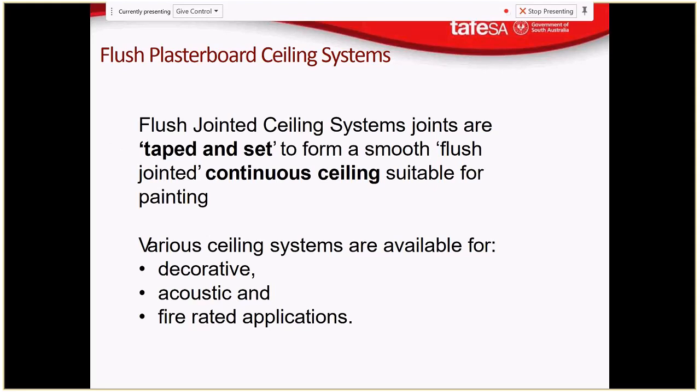Well, yes, plasterboard or any, so I keep using proprietary terms, sorry, but any plaster or gypsum sheet does have a small R value. Typically, R values are around 0.05. I think it provides a very minimal insulative value, but it provides some insulative value, and it certainly stops the simple transmission of air. So it stops drafts, etc.